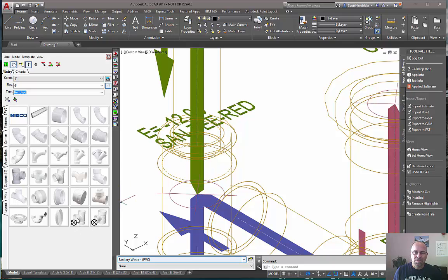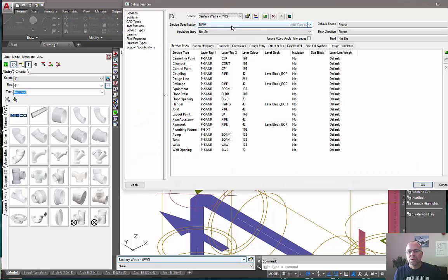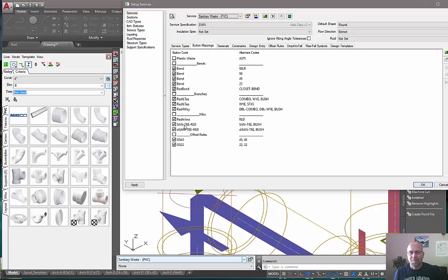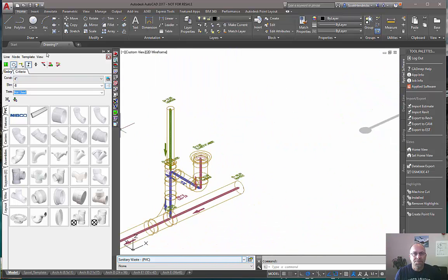It came to this button, but there were no parts for it to fill with. So once it finished looking through all the buttons, it went over to my button mappings and found that exact button code. And in that button code, I told it to use a Santee with a bushing. So it tried it, everything fit, and so it filled. So that one's good.